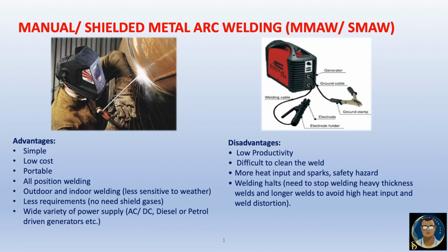But we can easily continue the SMAW or stick welding in this weather, because here the molten weld pool is not protected by the gas, it is protected by the molten flux, which is a flux cover for the filler metal. Wide variety of power supply: AC, DC, diesel or petrol driven generator, whatever generating current you can use as a power supply. So these are all flexibilities of this stick welding.